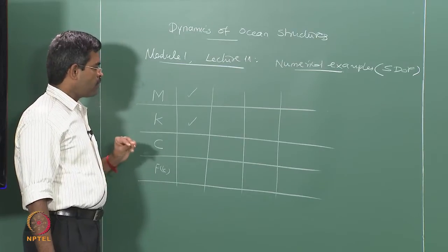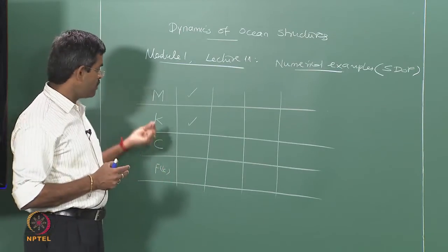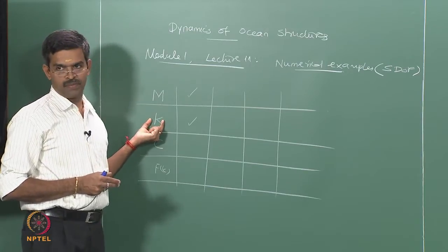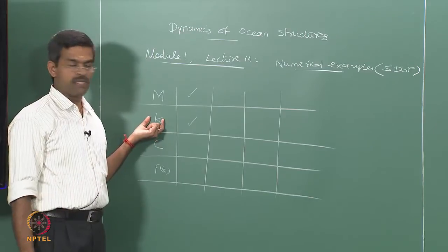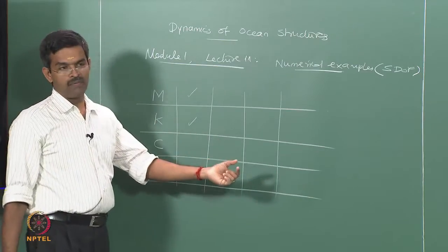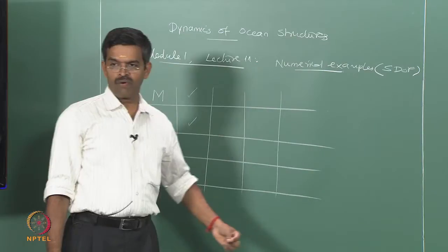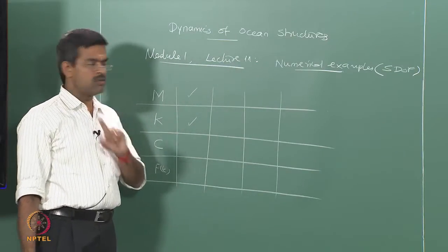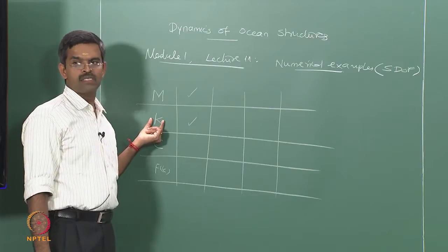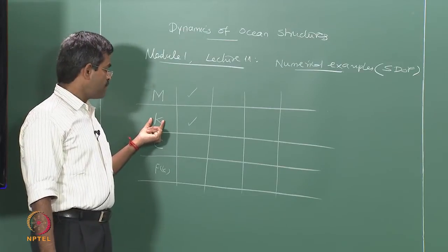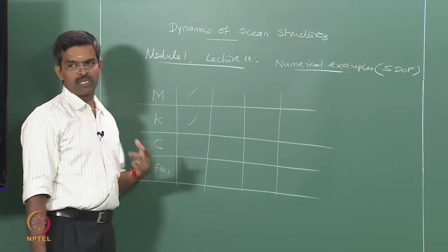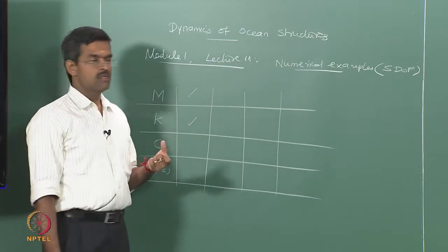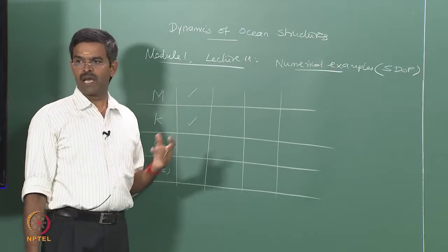And generally offshore platforms are designed in such a manner that one must get a very commendable restoration capacity or recentering possibility, be it gravity based platform, jacket platform, compliant system, or even semi submersible. One must ensure that there is proper recentering, so that the displacements or vibrations given to the connecting elements like umbilical cables and pipelines are minimized, so that exploration and production can happen conveniently.